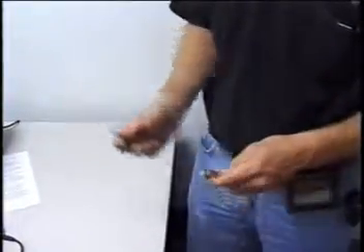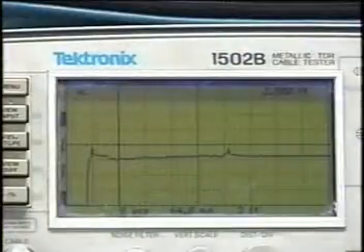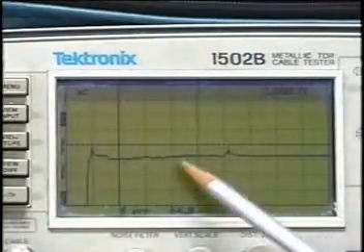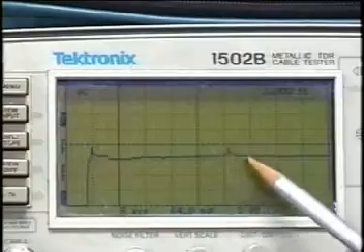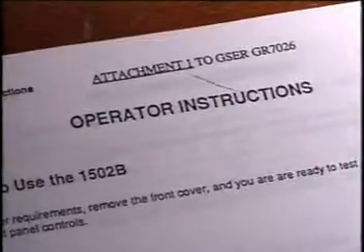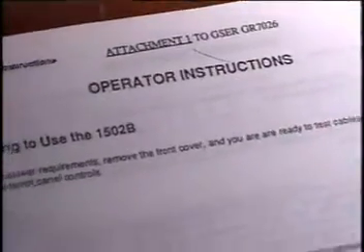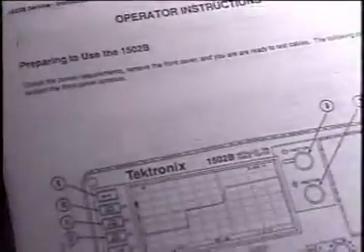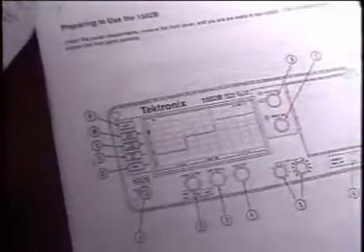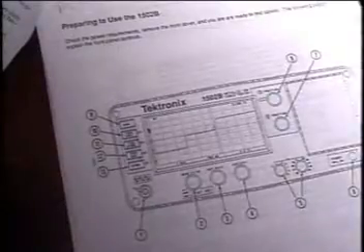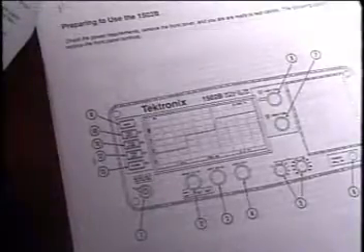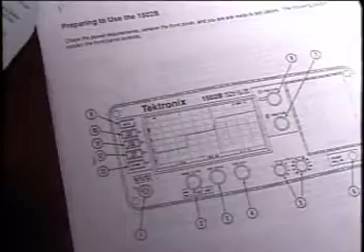Develop your skills by connecting practice cables with known defects to the tester and noting the results. Familiarize yourself with the TDR's many features and imagine work situations where they would be useful. Practicing with the unit under the supervision of a skilled operator is the best way to become an expert.